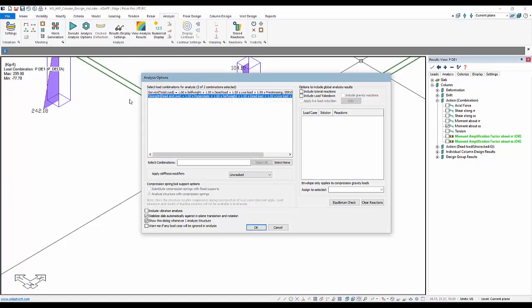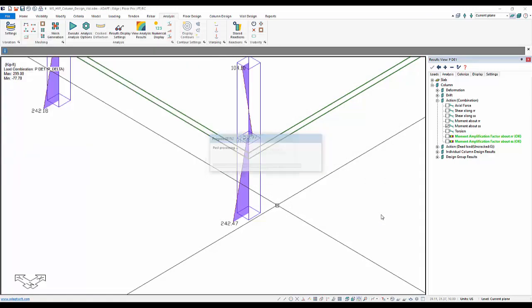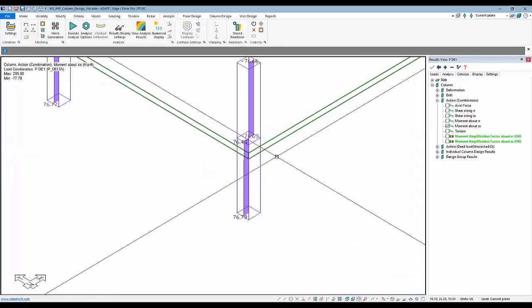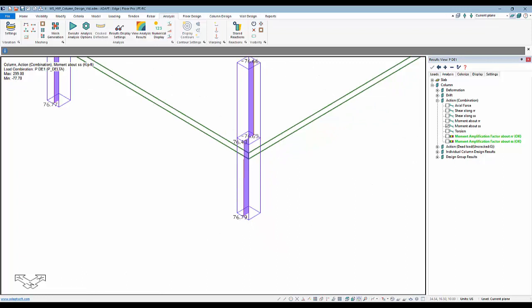Okay, I'm just doing this for this strength, dead, and live, which includes self-weight, dead, live, etc. And the objective here is to say, okay, I've just run the sacrificial combination to be able to solve for hyperstatic. What is the hyperstatic moment? Well, here for PDelta, when I ran it globally, I was able to use the combination result to see what that moment is. I'm going to go back to loads and turn on hyperstatic.